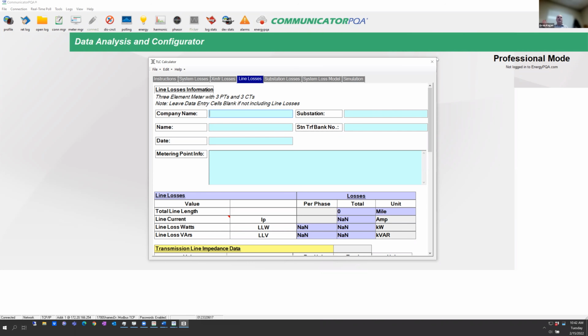So it's really a lot more cost effective to meter on the secondary side of that transformer. However, there's losses in that transformer. That transformer will generate heat. It'll have losses, and as a result, the utilities have developed a structure to be able to calculate what those losses are and kind of bump up the energy a little bit to account for them. In that area, this is how you do it.